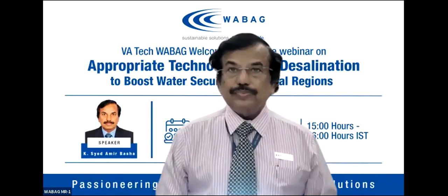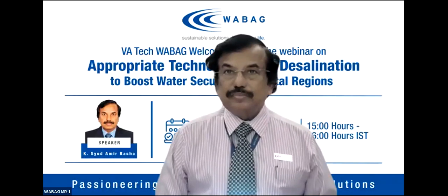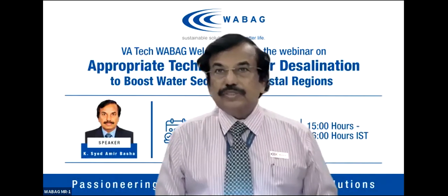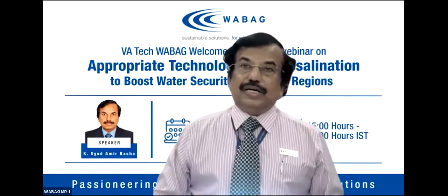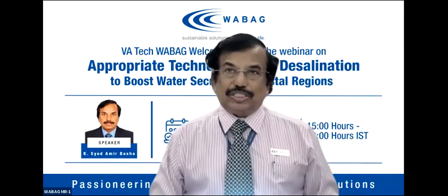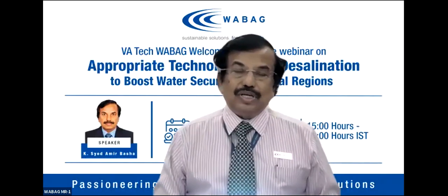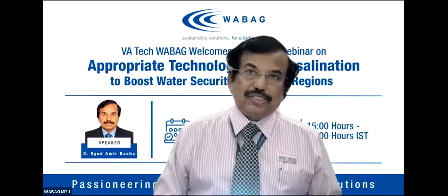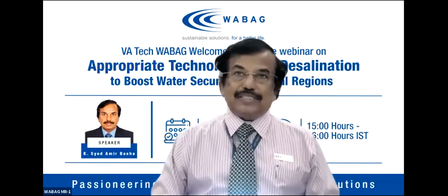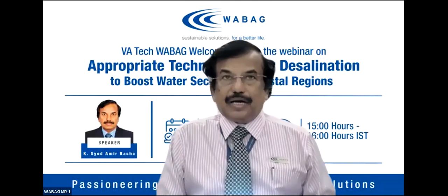Next question is from Mr. Madhman. What is the approximate cost of desalinated water through SWRO in large capacity plants? See, in the last 10 years, the water cost of international plants has come down from around $0.6 to $0.43. These are international plant prices, where the capacity of the plant is about 300,000 cubic meters per day, or 300 MLD.